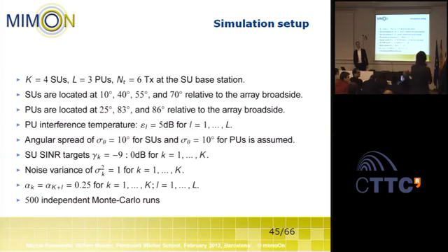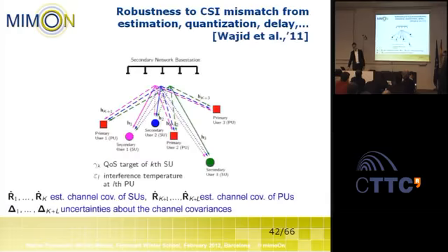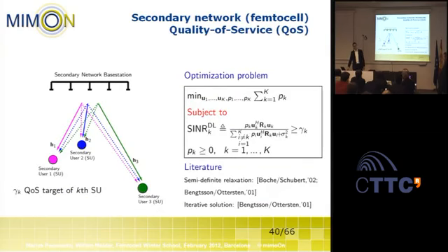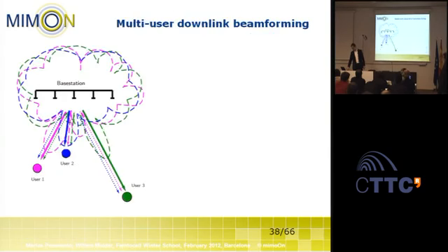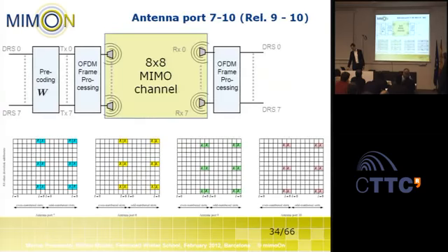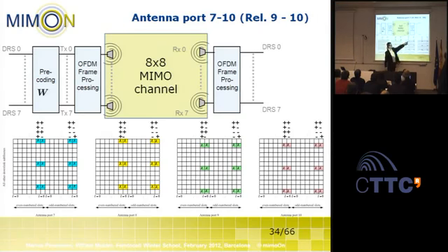Thanks for your talk. I just have a question about antenna ports 7 to 10. Do they have a larger density than the other antenna ports, for example 0 to 3? No, it's actually less. They are less dense. Also because if we look here, they use the same resources for different sequences.